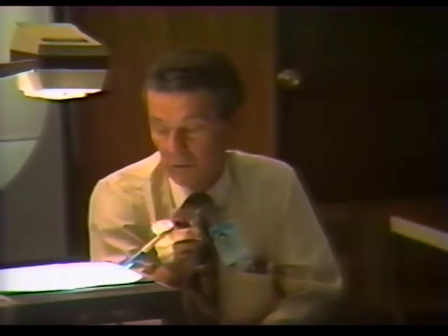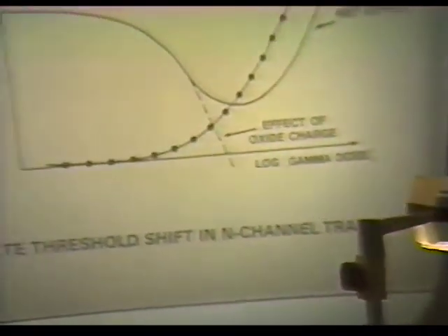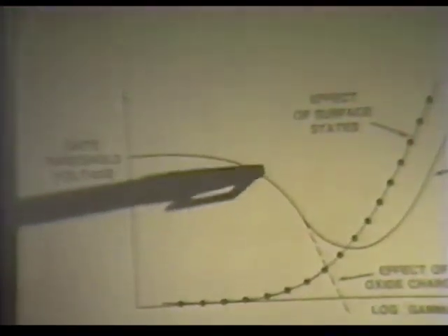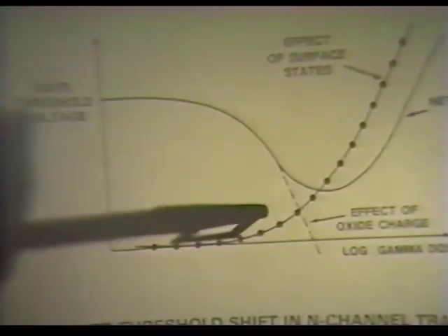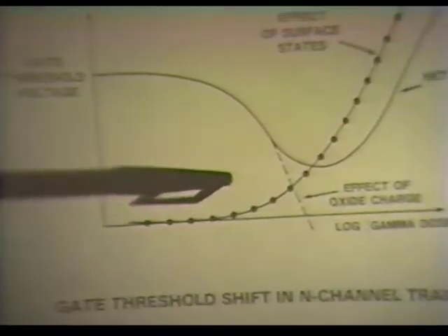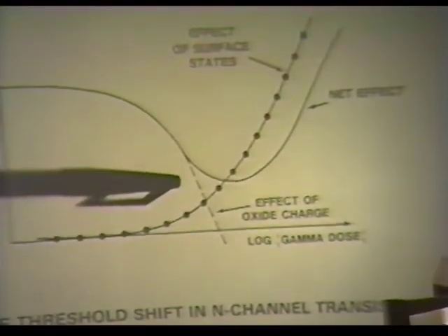Right there at the boundary of the oxide and the silicon, you've got some peculiar material that sometimes is referred to as SiOx, because it's not quite silicon dioxide. And you've got various types of bonding going on that create interface states that won't quite come out. That can sometimes help you too, because when you look at the threshold voltage on the CMOS that we build here, it goes out to about somewhere near 10 to the 5th before it starts degrading. That is, you build up enough oxide charge that you are starting to change your threshold voltage.